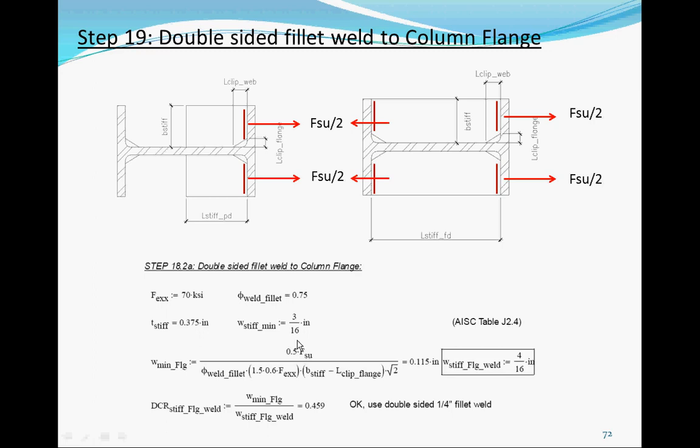This is what you should be calling out minimum, because that's greater than that. For ours, our fabricator wants to use pretty much one size weld if possible. They don't care if it's just a little bigger, because for their guys, they want their weld all the same. That's not just cost savings, it's more of a quality control. For the welders, all they do is, oh, I'm doing a Simpson connection, 1/4 inch weld is all I do. So that's pretty easy for them.